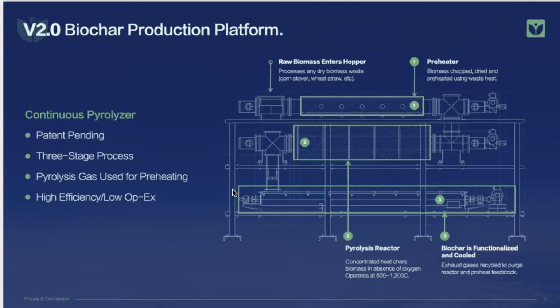What we found in our research is that most pyrolysis systems will operate at 300 to 500 degrees centigrade. And at those temperatures, you're going to produce a biochar that has a permanence of, say, 100 years in the soil and might have a pH in the 8s or the 9s. Our reactor, through unique design elements, can operate at up to 1200 degrees centigrade if needed. Now, we usually don't go that high. We're usually at about 800 to 1000, but at those temperatures, we get a much higher value product out and a much more consistent product.